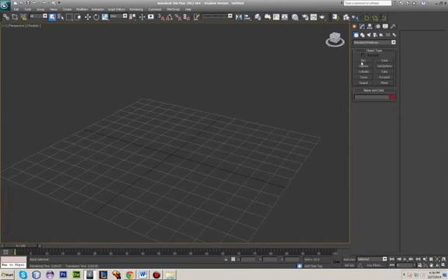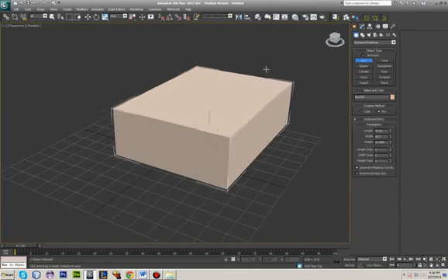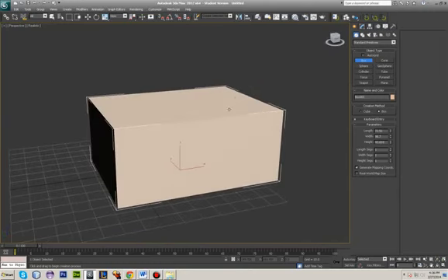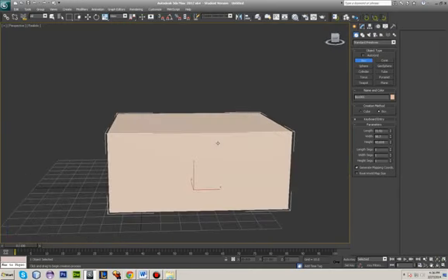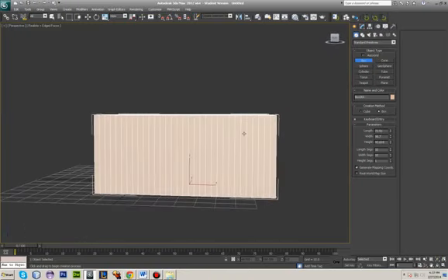First step is to make a box. I'm going to make a box around that big, this tall. And this is going to be where the water will be coming from, like a base, and the water will be just falling down right here. Okay, I want this to be 32 segments long to 32 segments width, and we should probably, there you go, turn that on, F4.